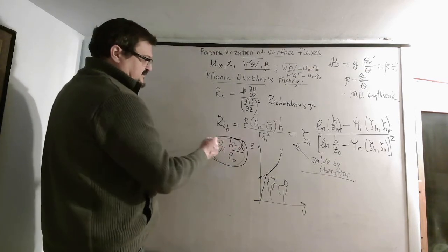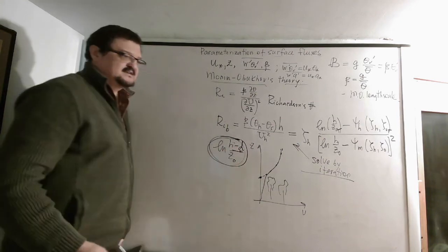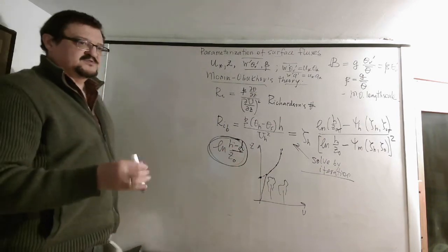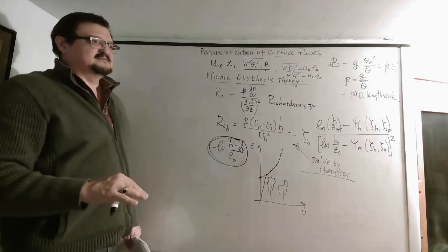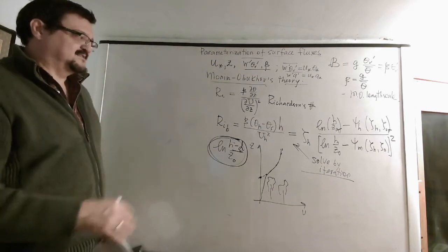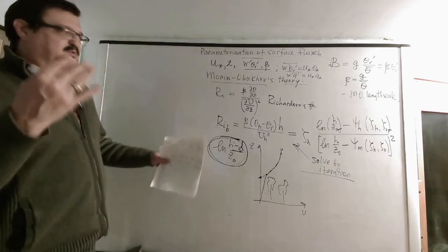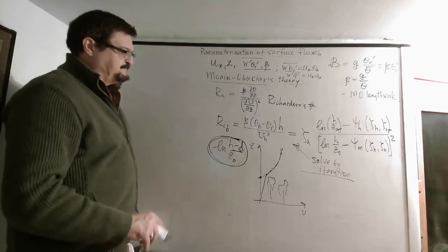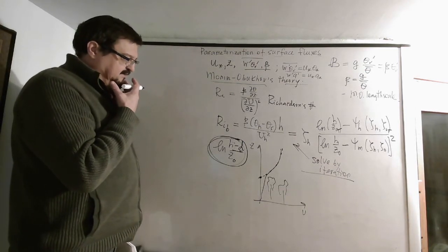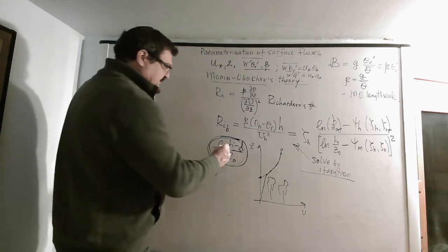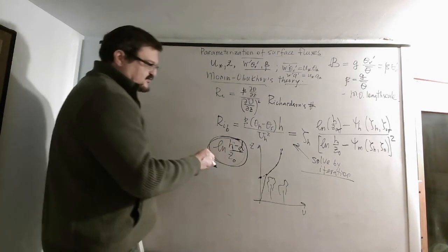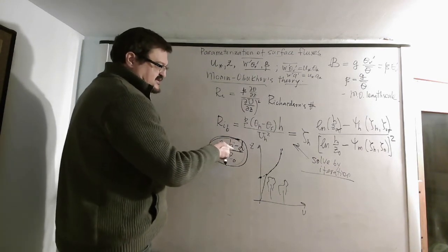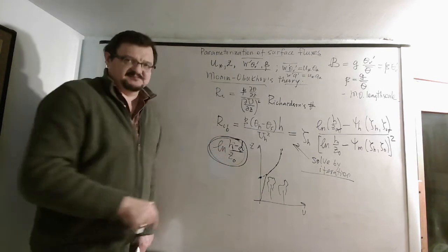Generally, displacement height is parameterized in terms of obstacle height. Let's say 10% of obstacle height, or 50%. It depends on your land type. So from this you see that it should be positive, so your h should be for sure higher than the displacement height.